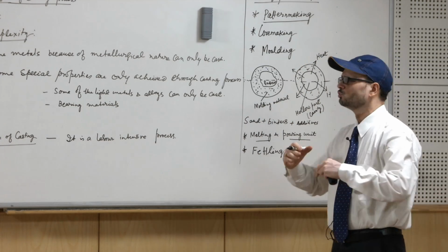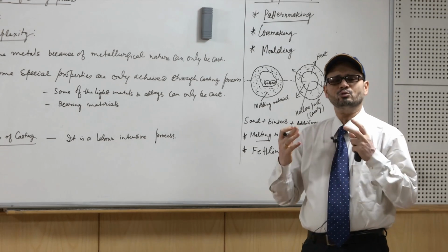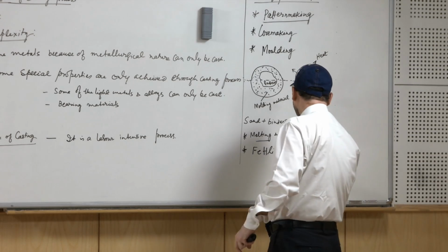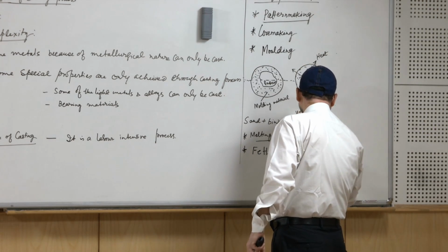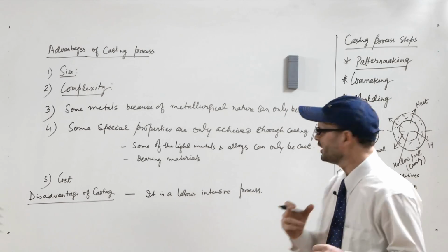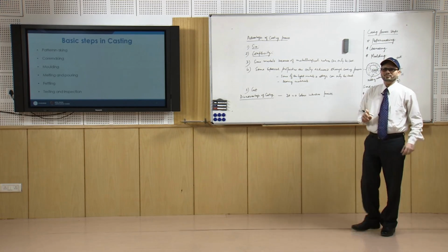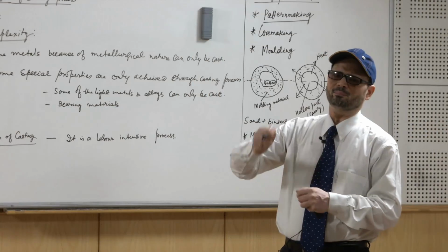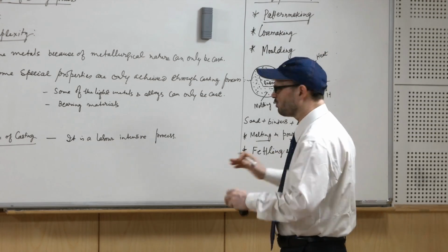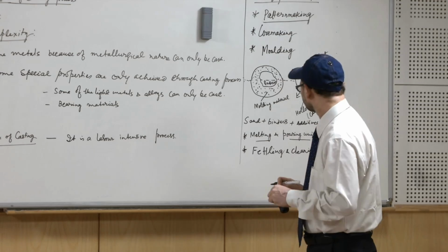You have to basically also clean the unburnt sand, you have to clean the scale, all this fettling and cleaning, these are done so that you can further use this material. So, in this case you have the provisions for either breaking the extra attachment, or you may go for cutting these attachments by flames or by electric torches.